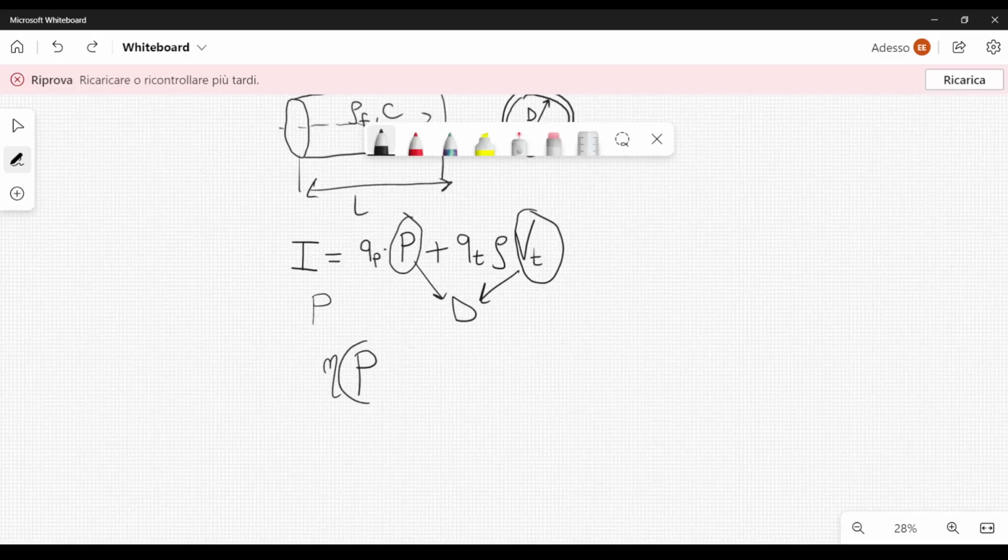So not all of this power will go to the fluid, because some of it will be lost, and ideally we want eta to be as close to 1 as possible. And this will be equal to, in general, with this, we need to cover the energy losses of the fluid inside the pipe. And these energy losses can be obtained by using the volumetric flow rate that I will call Q. So this is volume per unit time, the volume of fluid which passes through this pipe per unit time, multiplied by the